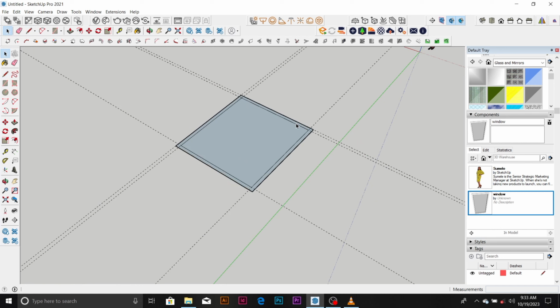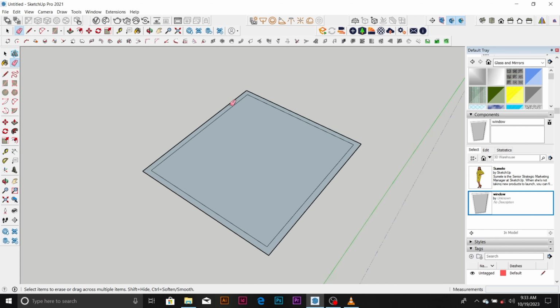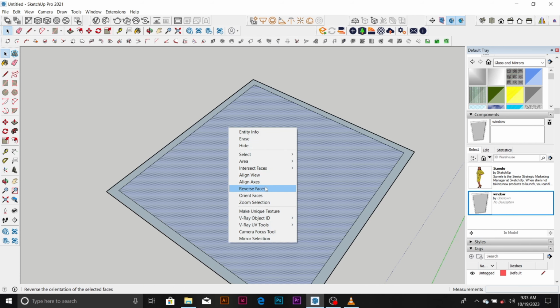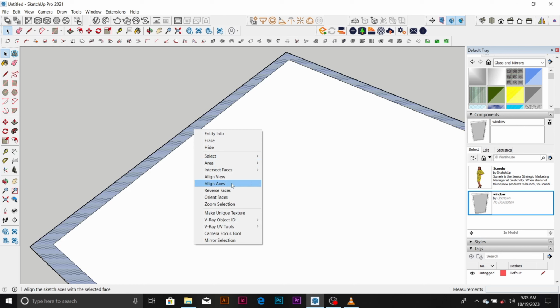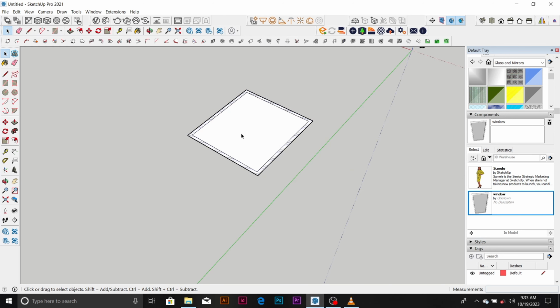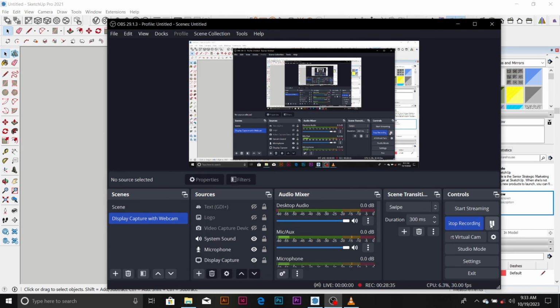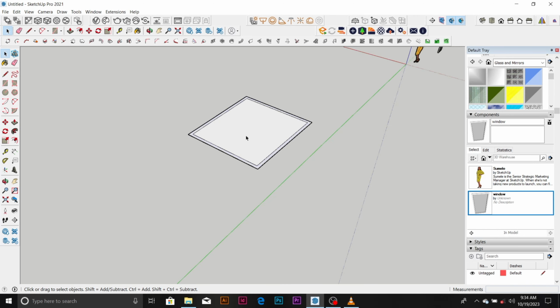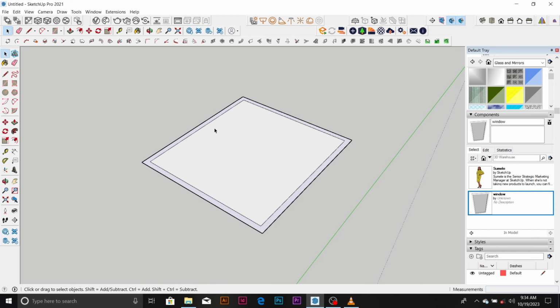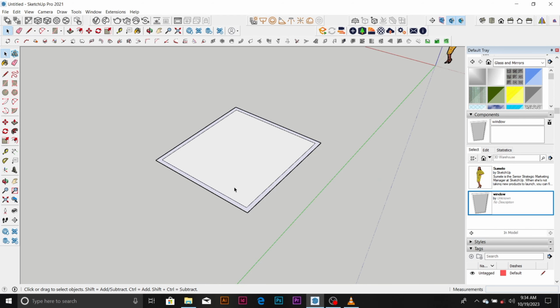So we have created the floor plan using line tool. Use line tool to create just one room floor plan. Reverse it. So we use line tool to create this floor plan now. So we are seeing the drawing. We are going to be adding depth. Use push pull. We want to add window and door to this drawing now.